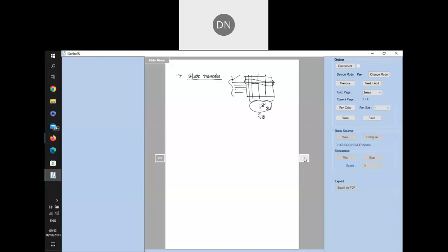Static memories are basically built using what is called a one-bit memory cell. One bit of memory cell is designed using what we call a latch or a flip-flop. So let's understand how a memory cell of 1 bit size is implemented in a static memory. We know that a bistable latch like this is the basis for any storage. We have studied this when we built flip-flops and latches.